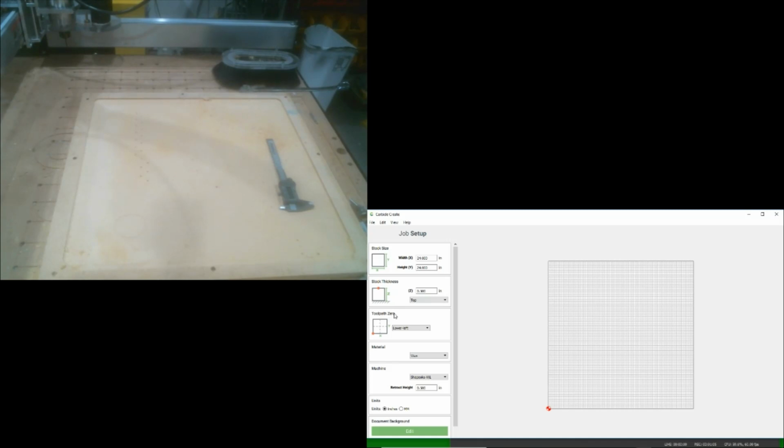Toolpath 0. Now, not where does your machine home, but where is X, Y, 0 for this particular job? And these are your options. 90% of the time I go with center, unless my stock is already the size that I need it to be. And then you've got to do a little more work. But if you do center and the piece is going to be cut out anyhow, then it works every time.